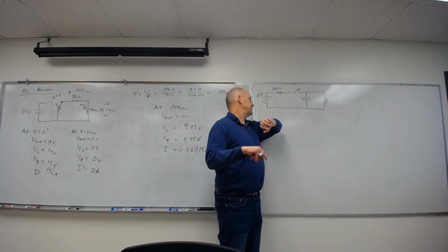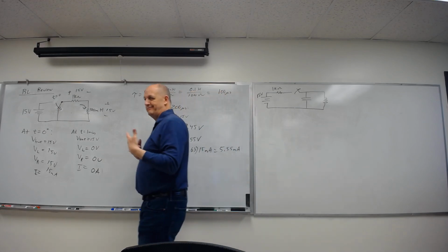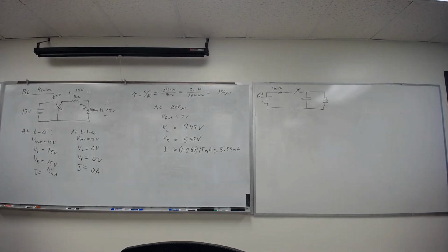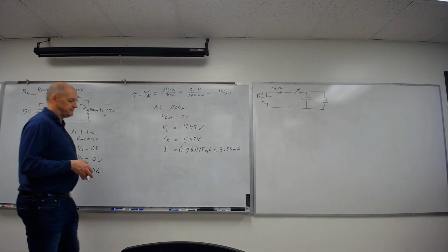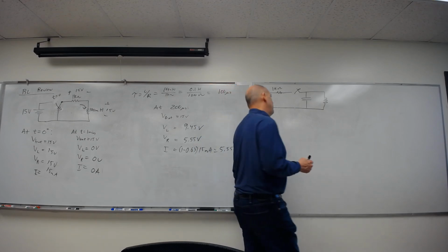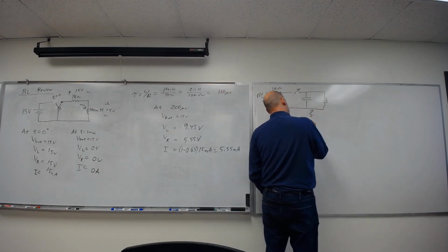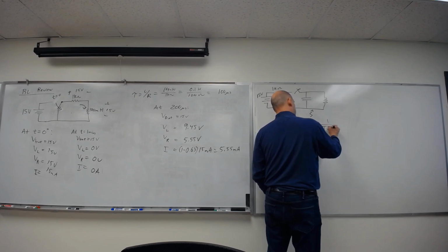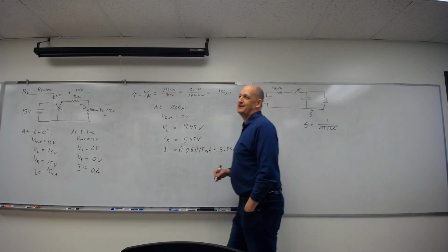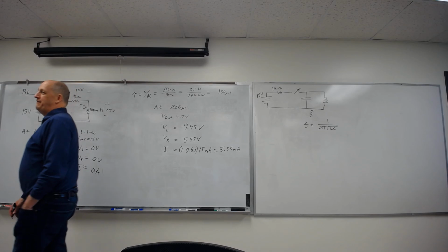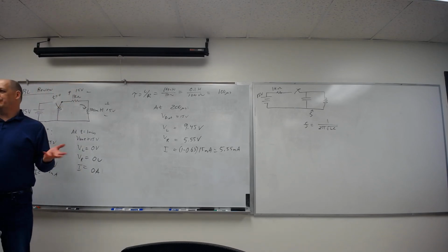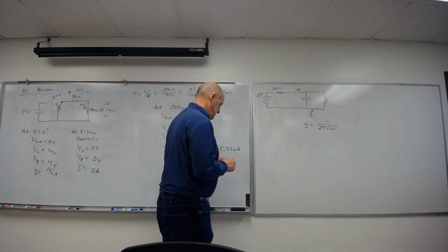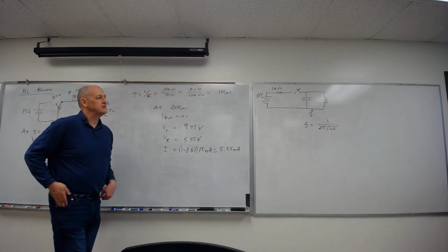The idealized version of this is like a perpetual motion thing. Now, of course, these have real resistance, so over time they'll lose energy. But it sits there for a long time. How quickly will this go back and forth? 1 divided by 2 pi, square root of the inductor times the capacitor. That will determine how fast the energy goes back and forth, because it's like a sine wave. But it's really a DC circuit where we just have a capacitor and inductor connected together.